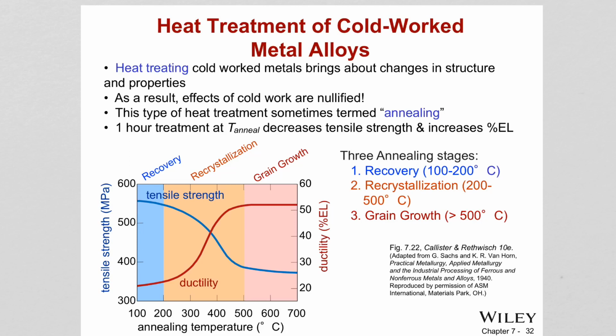Because then in your processing you need to apply more and more stress, and the material is becoming brittle because it is becoming stronger, which makes it impossible to keep working on the sample, for economical reasons and simply because the material is becoming brittle.